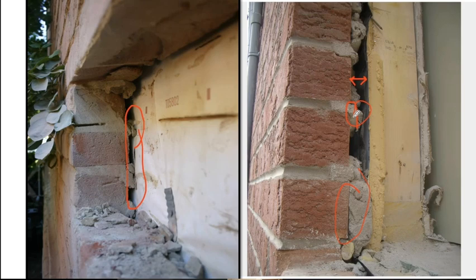hard to police that. So the water resistive layer in this picture on the right is the aluminum foil facing on the polyisocyanurate insulation. Here's polyiso insulation. That's what I'm doing right here. There's my iso. This is my wood stud, right? So you can see, in fact, they have a double bottom plate here because they're going to pour a floor topping. And this building hasn't had any leakage problems.